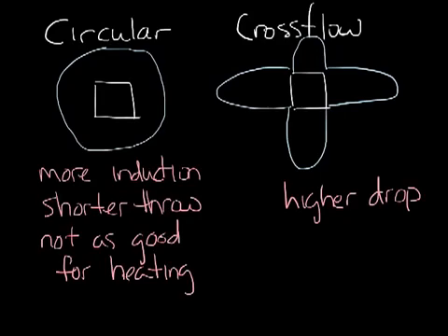One last thing on air patterns. If you have a diffuser in your office, take a second to look up at it. Is there dirt on the ceiling around the diffuser? You often see dirt around the corners of a cross-flow diffuser. We call this smudging. The dirt isn't coming out of your diffuser, it's coming from the induced room air.